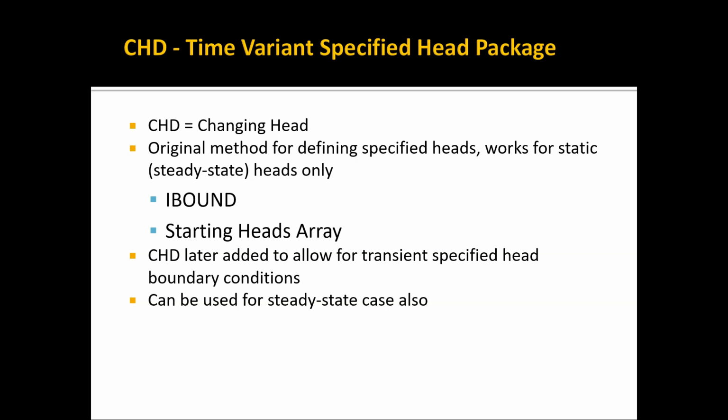package. Now, by the way, at this point I should pause and emphasize something here. How does a constant head boundary condition work? Well, it's either a source or a sink. Let's suppose I have a cell that I mark as a fixed head cell, and typically you would only do this to simulate either a river, a rather large river, or a lake.